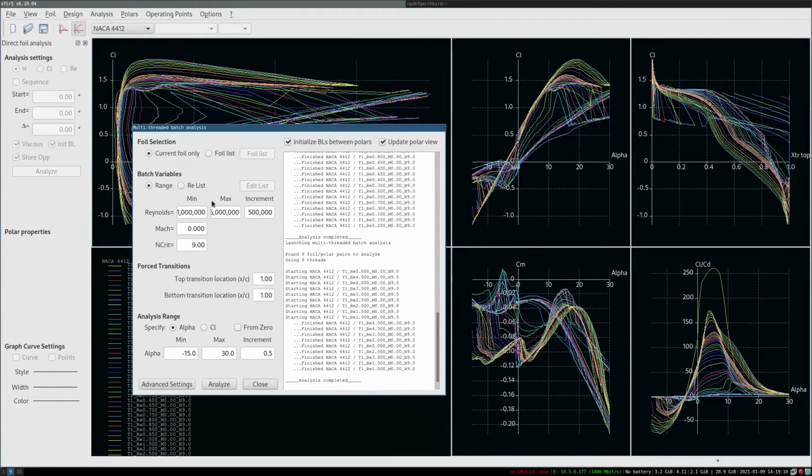Now there is one thing to note, which is obviously DBF scale aircraft. Why would I ever need a Reynolds of 5 million? And the answer to that is very simple. With the variations in chord on both of your main lifting surfaces, be that your wing, biplane wing, or your full flying wing body, from the tip to the root, as well as at different angles of attack and different speeds, when you do the stability analysis, you may find that in some edge cases you are in the many millions of Reynolds, so this is why you need to run these points.